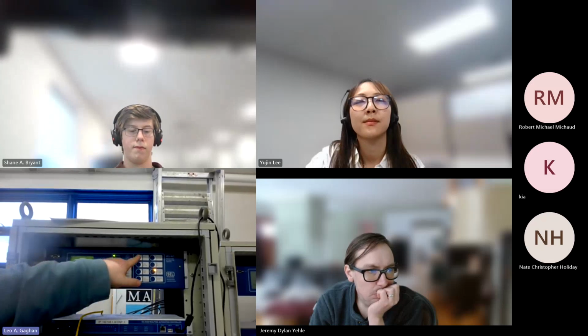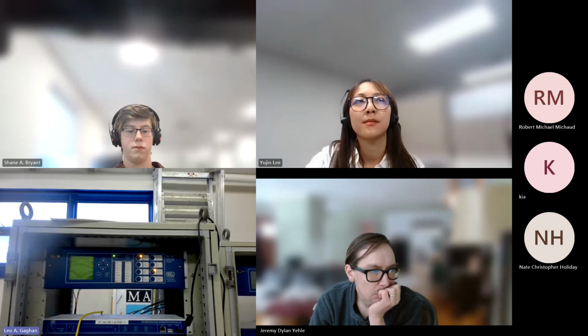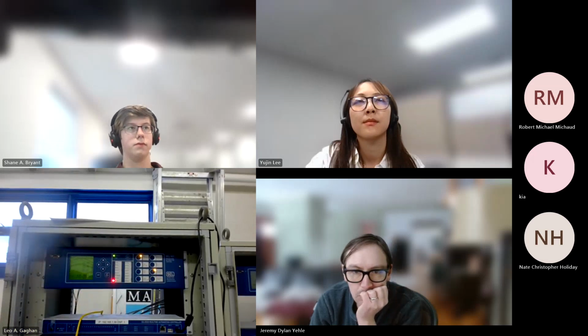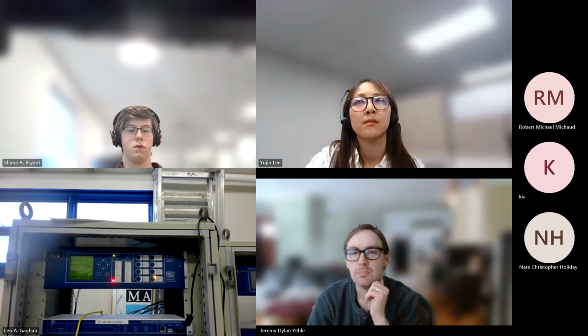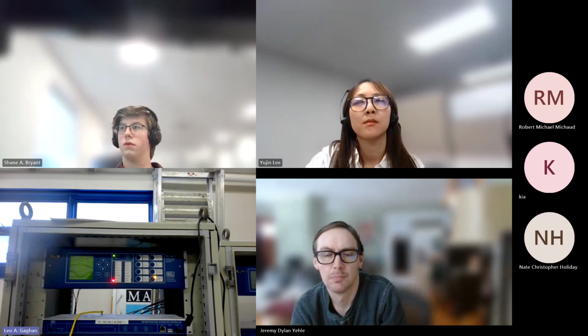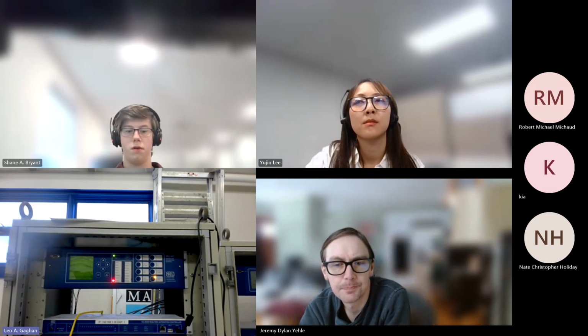Now with that, all right, I'll put it on 52 control switch. Now you can open and close it from the control switch. See the status changes right there. Take that off. Doesn't do anything. But now that control is enabled through our relay, we can close, open, close, open.